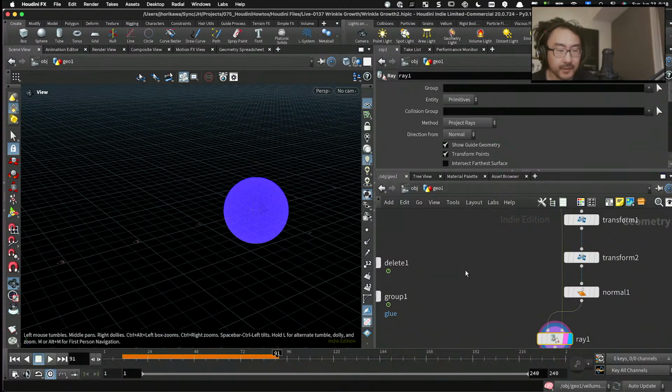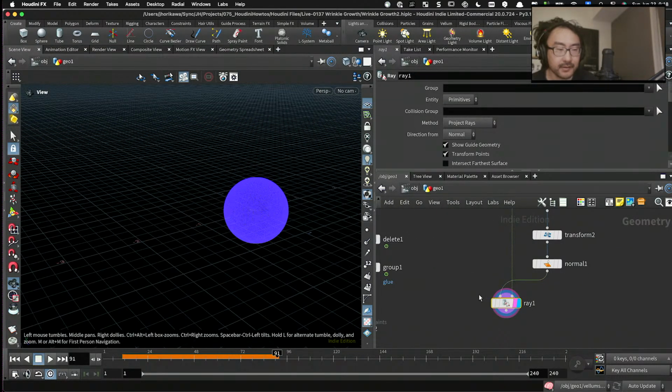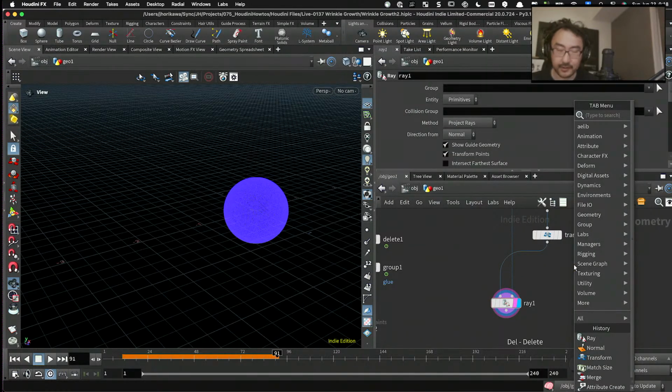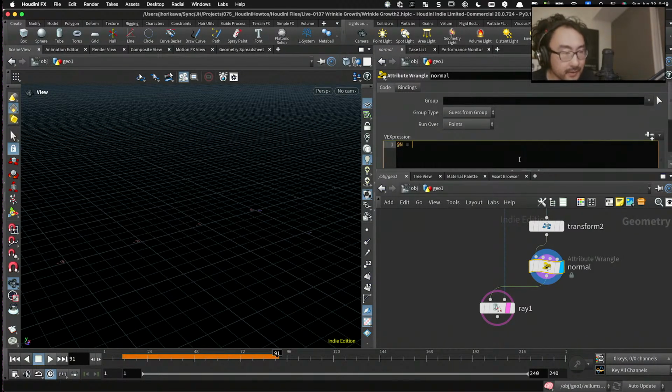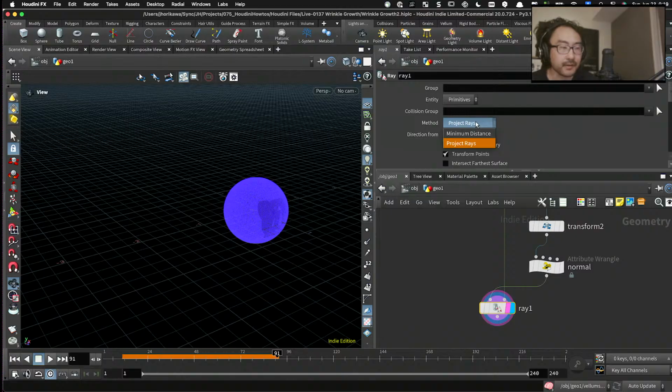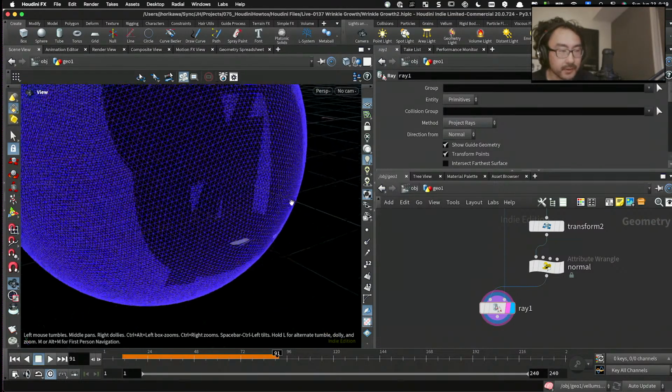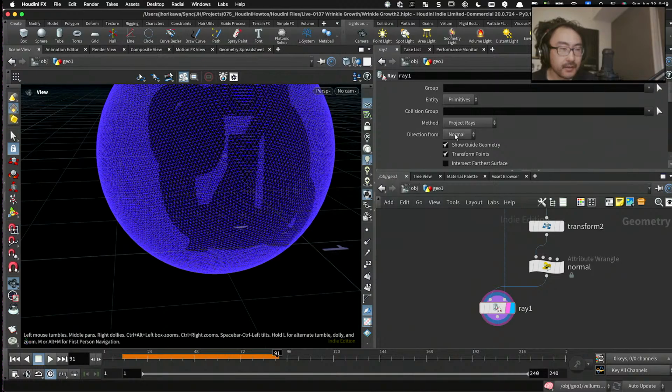I think it's not projecting because the normal is not facing these directions, so instead of using the normal node, I'm going to create a custom normal direction to project, which is -1 for Z. Then I think it just projected. Yeah. 4 points.